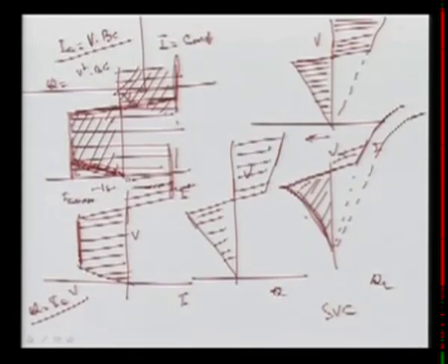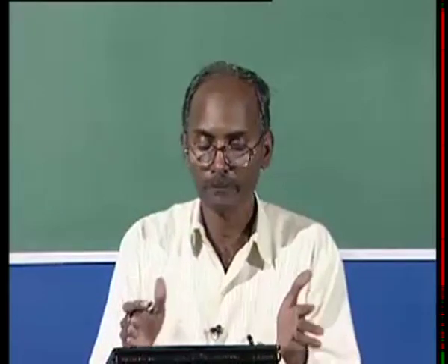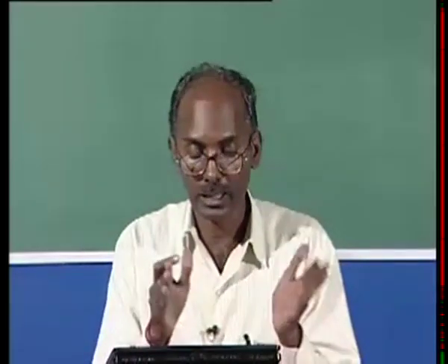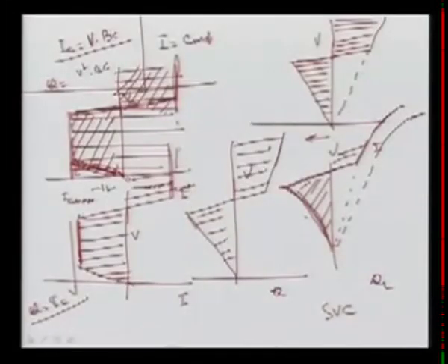So this STATCOM is better in terms of dynamic range. It has a wide dynamic range, a better operating range, and also more overload capability, meaning we can go for more current on both sides. Here only on this side can we go for more current, and normally we require it in this capacitive zone. So this is basically the difference between the SVC and the STATCOM.